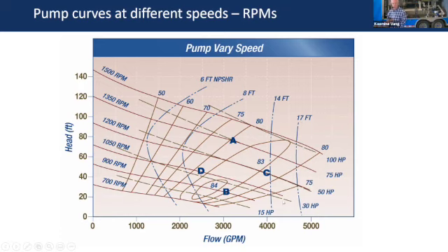That's why these pump curves stop right here, because they don't want you to run in this area over here because you could start cavitating and damage your impellers, cause pitting and stuff. So that's called net positive suction head. I can't say that I'm a super expert at it, but I kind of understand the idea. You have to have that pump submerged or have enough positive pressure into it so that you don't get cavitation. And that's what those blue lines indicate. Hopefully that answered the question.